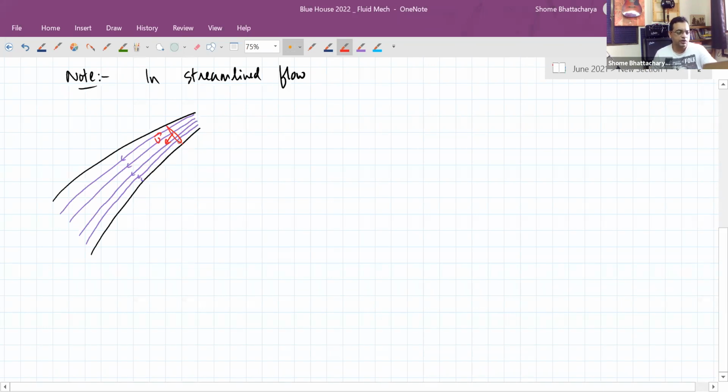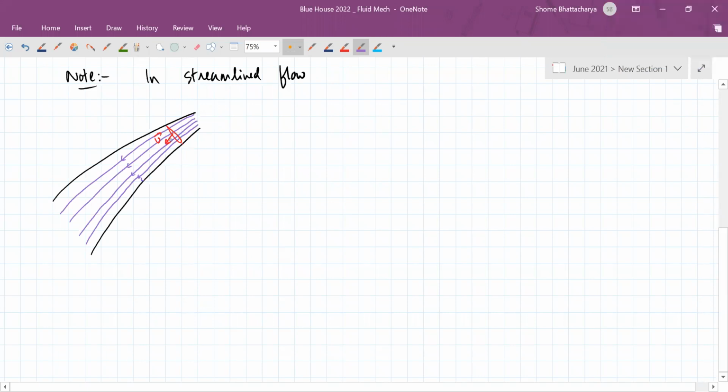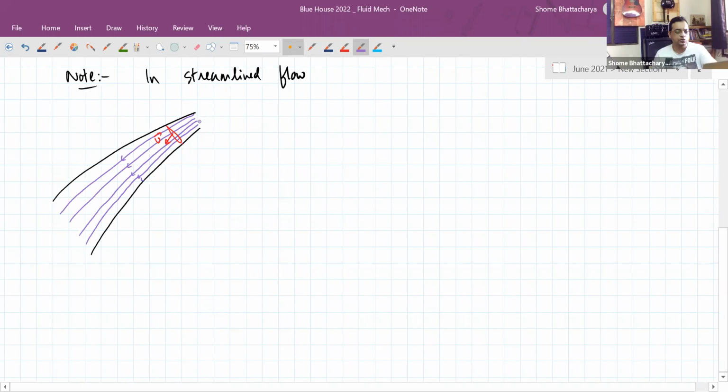And also, if you see one fluid element passing through that cross-section just now, and a little while later, another fluid element that was behind it follows its path and goes through that cross-section, the one that followed its path will also have the same velocity as it went through that section. And the next one following it will have the same. So the velocity of every particle going through the cross-section is not only same at a given instant of time, but also through time. Any fluid particle or any fluid element going through that particular cross-section will have a fixed velocity. So that's another important property of the streamline motion.